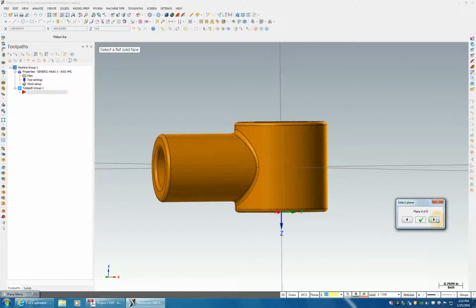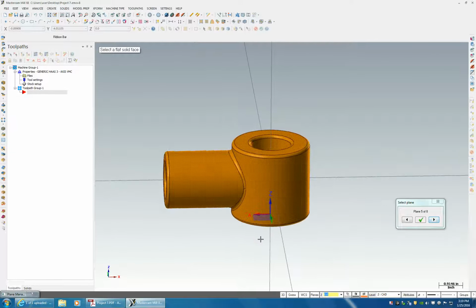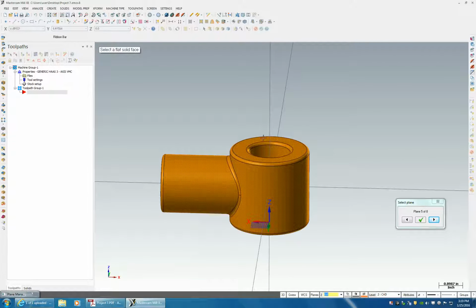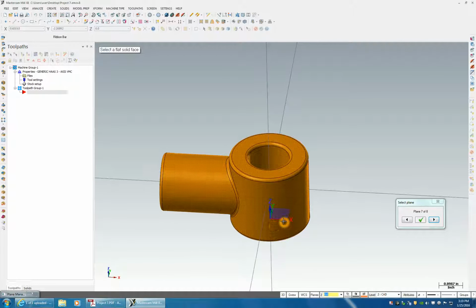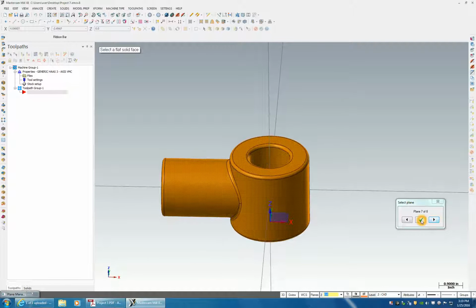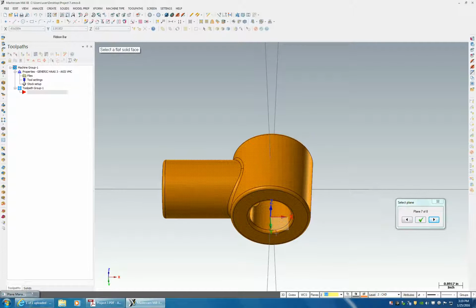So there is possibly an appropriate one. I'm going to say this is going to be laying in the machine where the negative X-axis is going to the right and to the left at this view. So this shaft is going down the negative X-axis. Right now it's saying it's going positive X. So we need to thumb through our options until we get this. That means our X is now going to the right, our Y is going up towards the back of the machine, and our Z is going up into the spindle. And it happens to be right at the center of our bore, which is good.